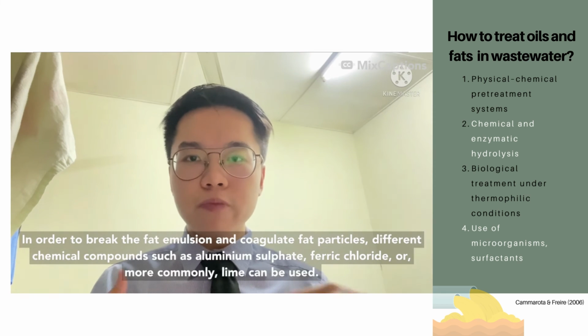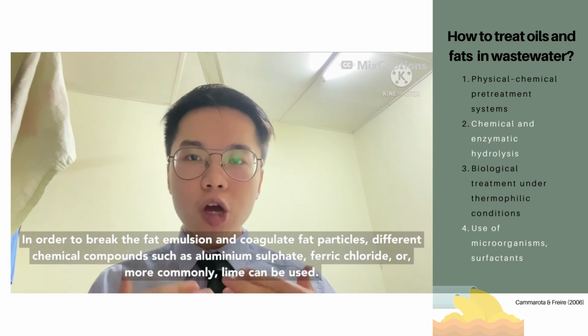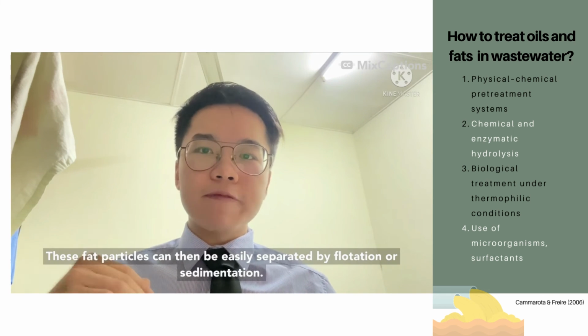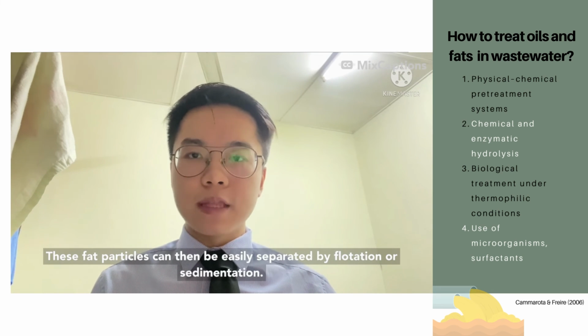end. In order to break the fat particle emulsion and also coagulate fat particles, different chemical compounds such as aluminium sulfate, ferric chloride, or even lime can be used. These fat particles can be separated easily by flotation or sedimentation.